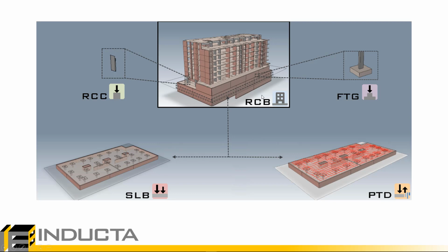And RCB cannot model tendons, so if we want to do a post-tension design, we have to send it to the PTD software. As we'll see in the coming videos, we can export multiple floors in bulk, have the SLB and/or PTD programs launched silently in the background, and then we can view their results in RCB without having to leave the RCB program at all during the preliminary design stage.